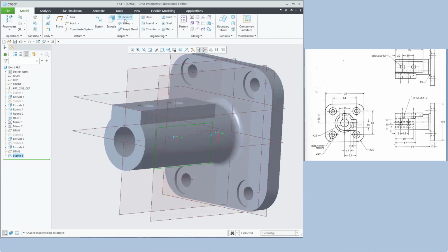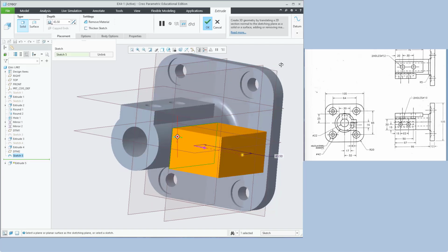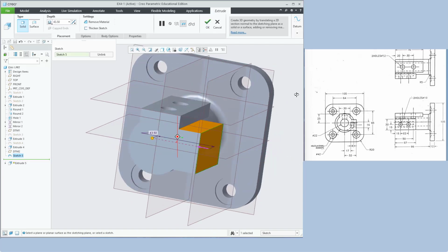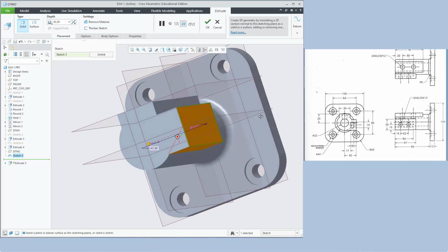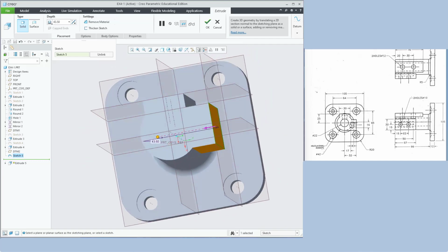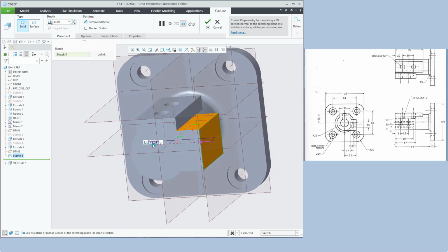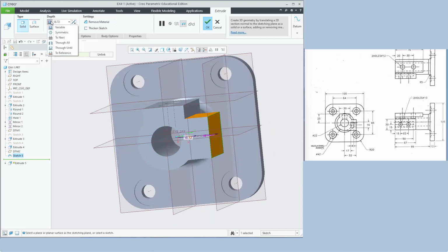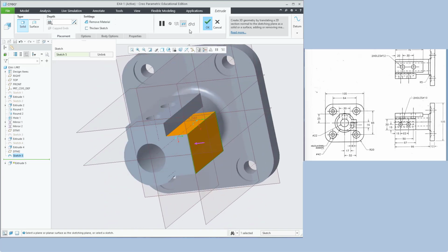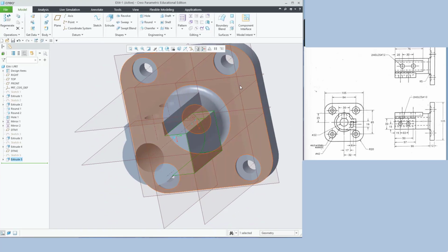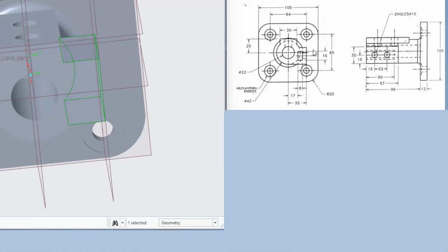Go to shading. Go to extrude. Change the direction. Okay. Only up to next. You don't want to fill it. The hole remains as a hole. You can see in the dimension. So just we will extrude somewhere here. Use the same option like the previous one, up to next. It will be connecting till the next. So finish it.